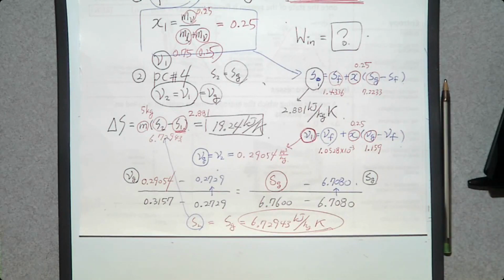If it is a solid like this one, we know there is no phase change. Then you use an equation to determine entropy that we are going to study today. What about air? Is there phase change? Not really, right? We have air, it's a gas, and it's going to be gas tomorrow, and the day after tomorrow it's still going to be pure gas. Then you don't use a table, okay?